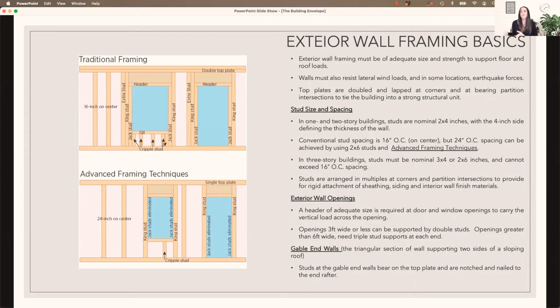That's going to be based on the regional considerations for the project, how much insulation is needed, and things like that. Most commonly, what I've seen are 2x6 stud frame walls on the exterior of a building, and then 2x4 walls on the interior. So you can really get that extra insulating factor on the exterior.